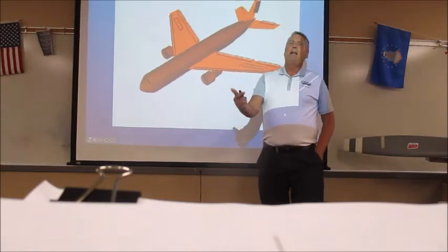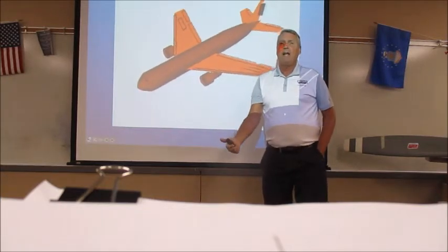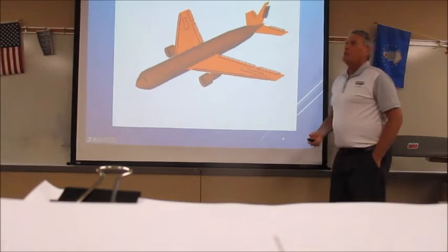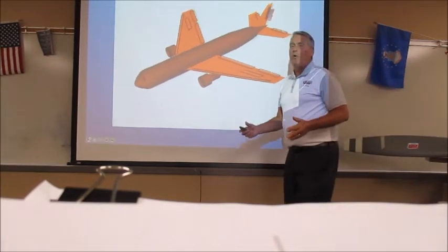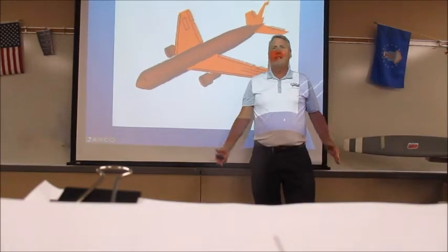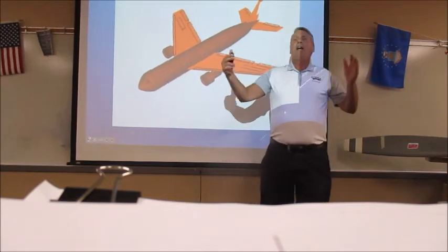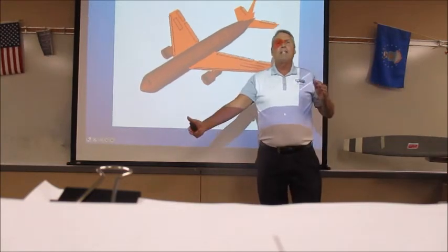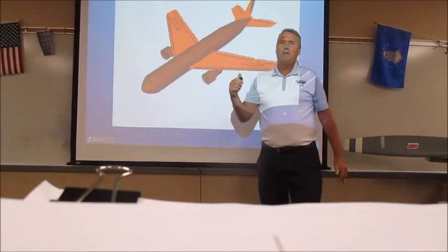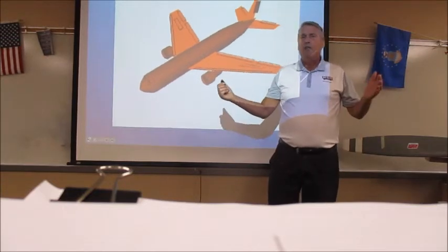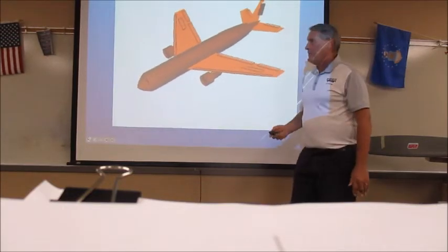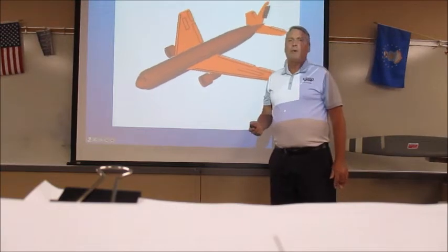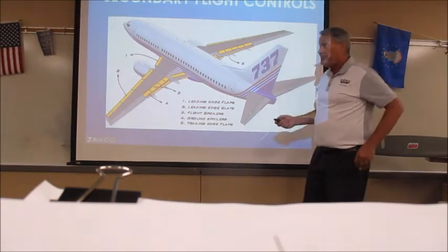Rudder, ailerons, elevator. Those are the flight controls you do not want to lose. You're going to have redundancy built in, and any kind of emergency power is going to be able to supply hydraulics out to these systems, because you definitely want your primary flight controls.